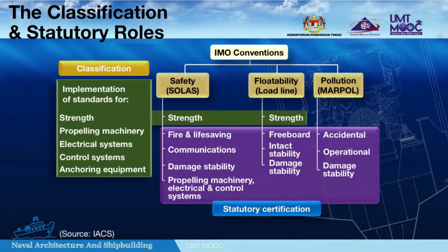The regulation takes into account the potential hazards present in different zones and different seasons. The technical annex contains several additional safety measures concerning doors, freeing ports, hatchways, and other items. The main purpose of these measures is to ensure the watertight integrity of the ship hull below the freeboard deck.